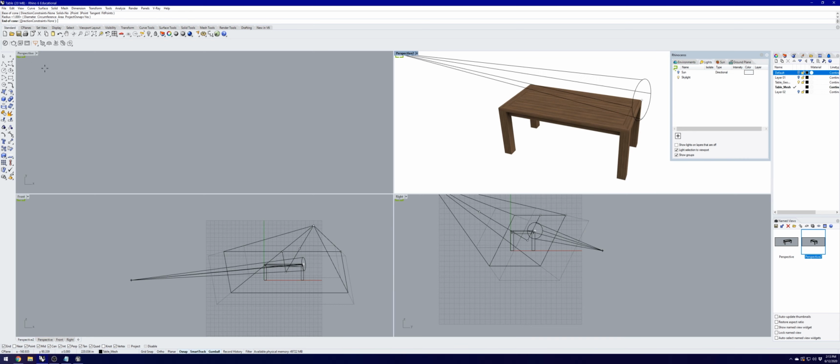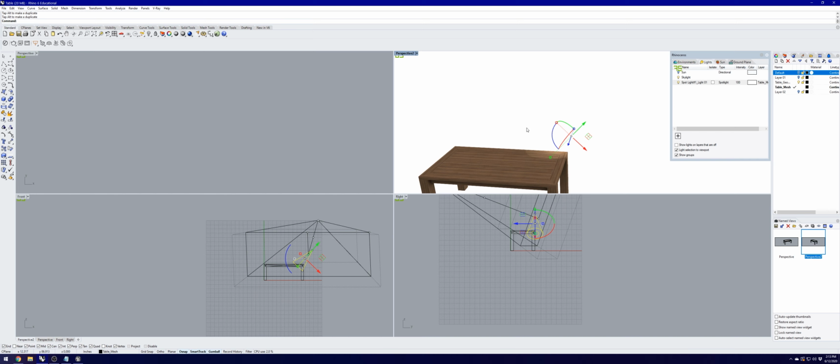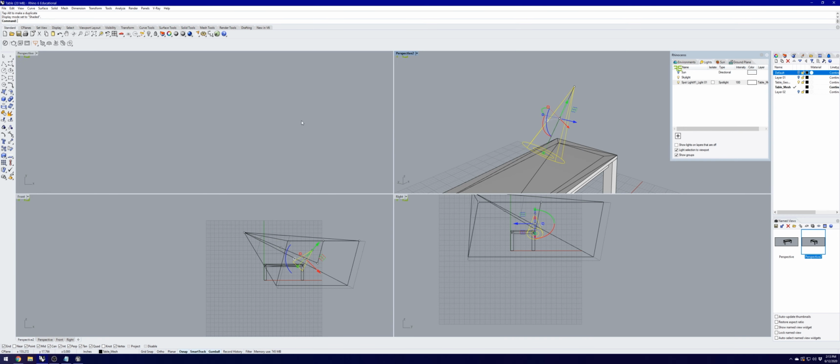And then I'm going to go into one of my side views and angle it in a way that looks nice. So what I'm going to do is angle it straight up, and then I'm going to rotate it. And you can see here in my rendered viewport, the light is being cast onto my geometry. And you can't see the light in the rendered viewport, which is kind of annoying. So you have to go back to shaded to get it perfect.